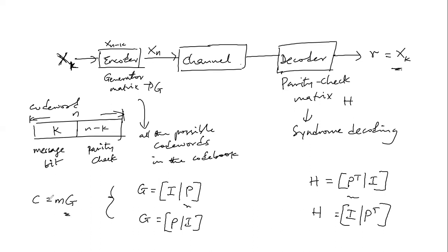Then we now have to multiply the message bit with the parity check matrix. And then we will now be able to get the parity bits. So once we have the parity bits, then we'll be able to establish our syndrome, as you'll see shortly, because all of those will take place right at the receiver.